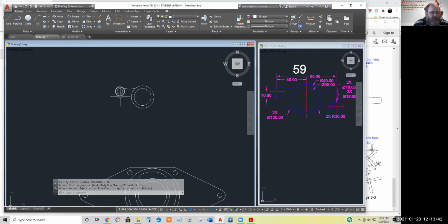Now again, if you try to draw the arc the same way, it will form concave. Not what we want. So sorry, a little more work. Let's go to tangent, tangent, radius and make a circle. We'll say, I want it to touch approximately there. I want it to touch approximately here. Last thing is specify the radius. That's half the diameter here. So we'll type half of 120, type 60 and hit enter.